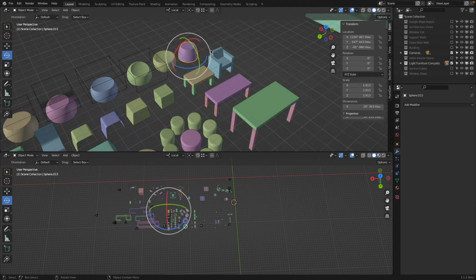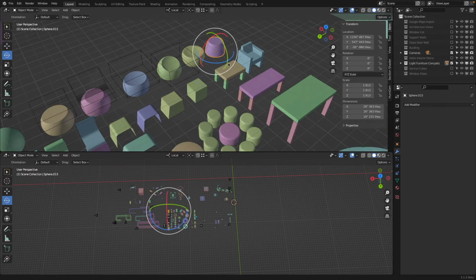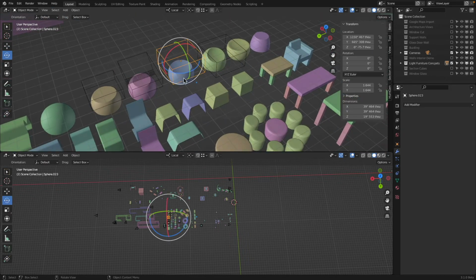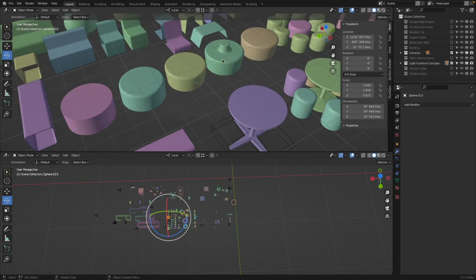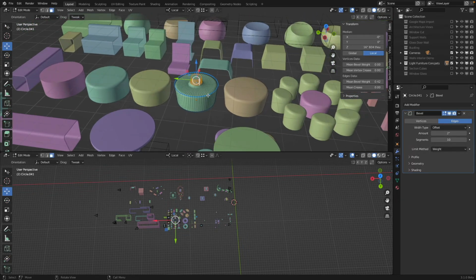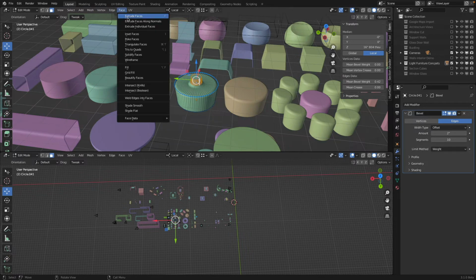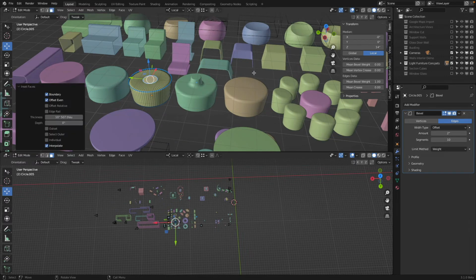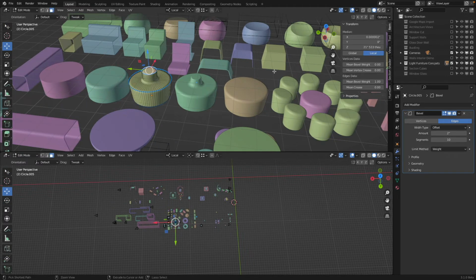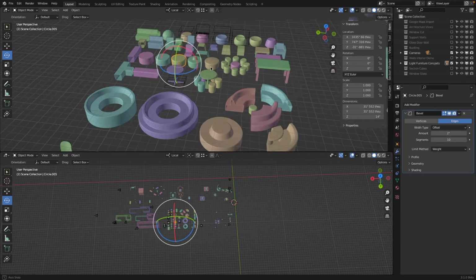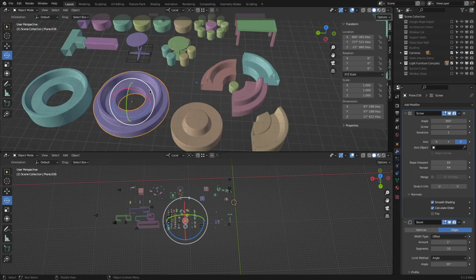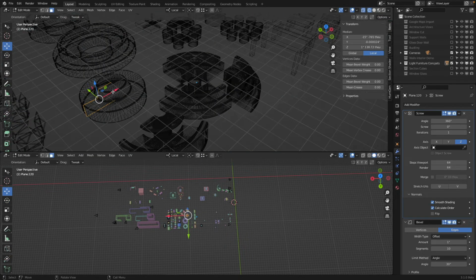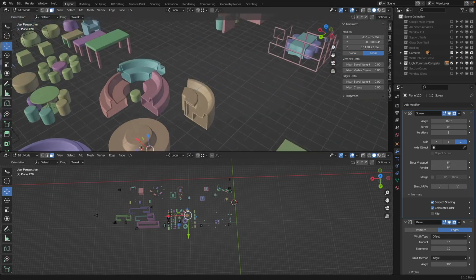There's actually a sphere where I started cutting elements. This is actually a sphere that's cut by a squeezed sphere. Here, for example, an extrusion in the inside up using the inset face. So when I had something like this, I for inset and E for extrude up. Not too complicated. Or what we learned about the revolve command here, turn this into a revolve. So there's a center point, but it's just going around.